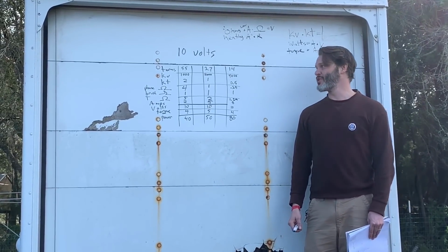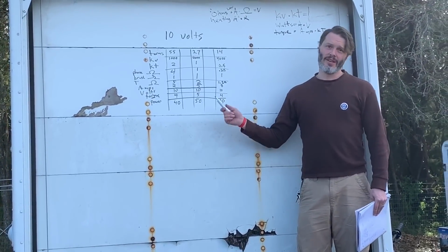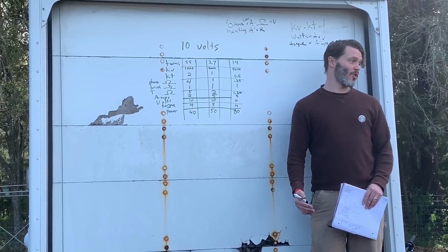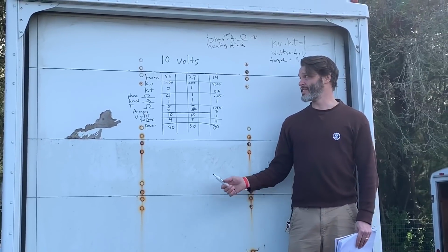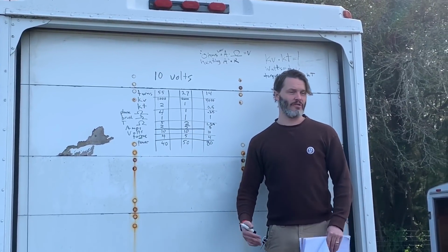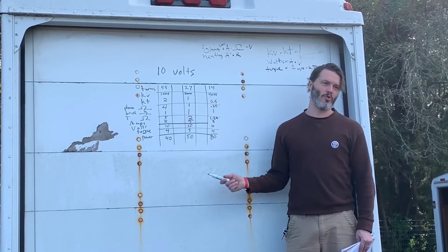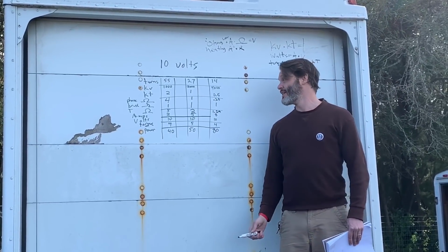So what can we do if we want to get more torque out of this system? Now you can always use a longer motor. A bigger motor is always going to be able to produce more torque before it saturates. And instead of having a 27 turn motor, we'd have a 21 turn 550. But it's the same speed. But since the resistance of the motor would be lower, you end up getting more torque out of it.